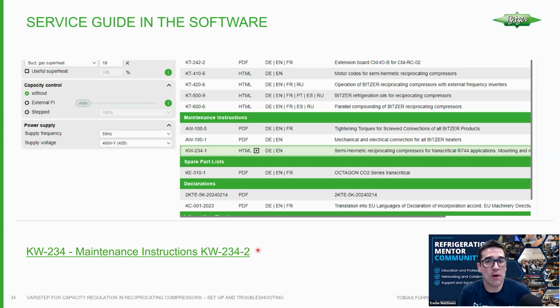No, but what is important is that if it's calling to load or unload and the sound doesn't change, then you will want to look into that, because maybe that solenoid coil is not working properly. You're not getting the output of the 24 volts to it, loaded and unloaded. Maybe that 0 to 10 volts is not working, like you talked about already.